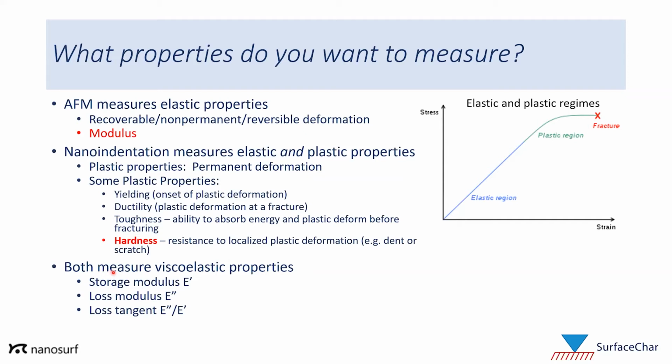Both techniques do measure rate-dependent properties, which are the viscoelastic properties, such as the storage modulus, the loss modulus, or the loss tangent, which is the ratio of the two. And this is particularly useful for materials like polymers, which are very viscoelastic.